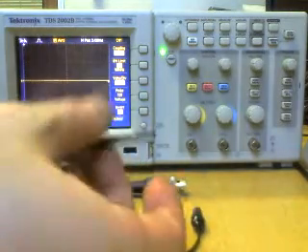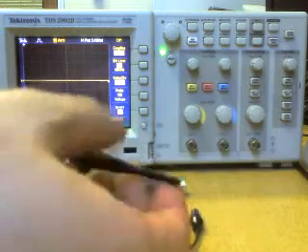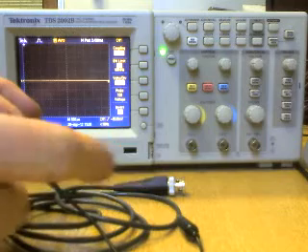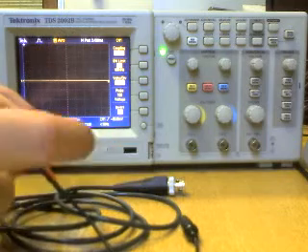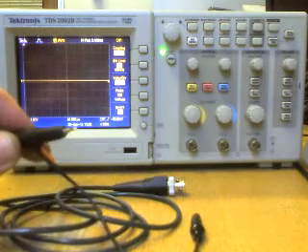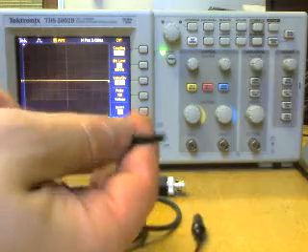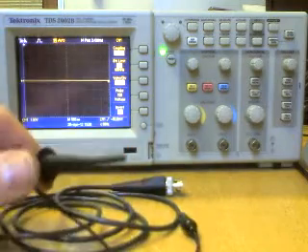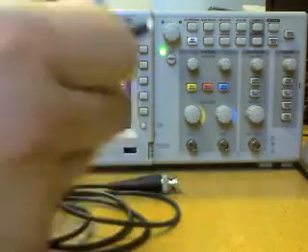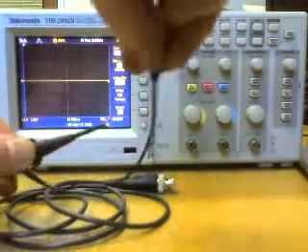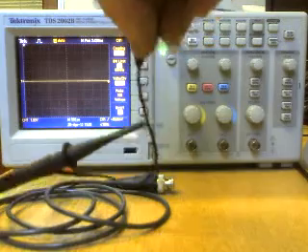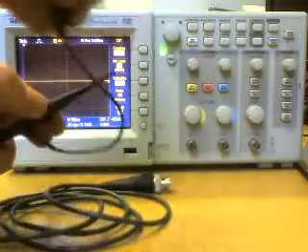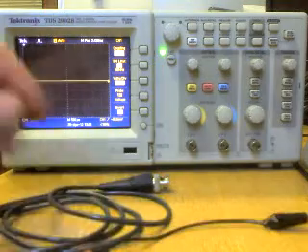And if you want to do probing about, you don't want to use the hook, you can actually unscrew this, and you've got a nice little sharp probe here. Be careful with that one, because you can actually stab your hand on it if you're not careful, okay? But always try and use the hook wherever you can, because you can hook it on. If this is your wire that you want to measure, your signal, you can hook it on and take your hand away. It's not going to go anywhere, it's nice and secure. Okay, that's what we like about these probes, okay?